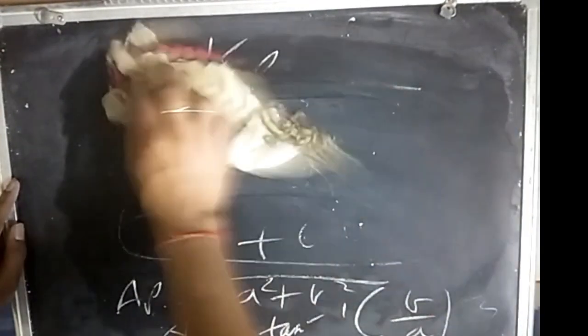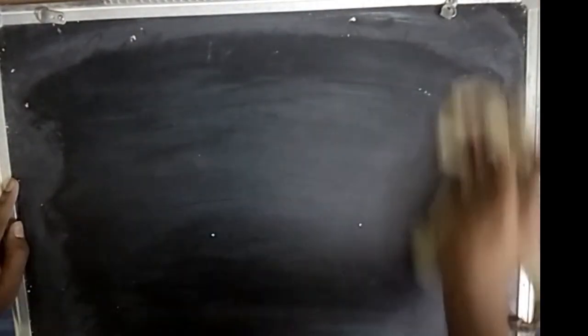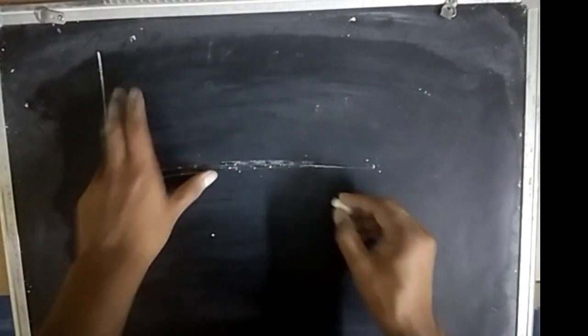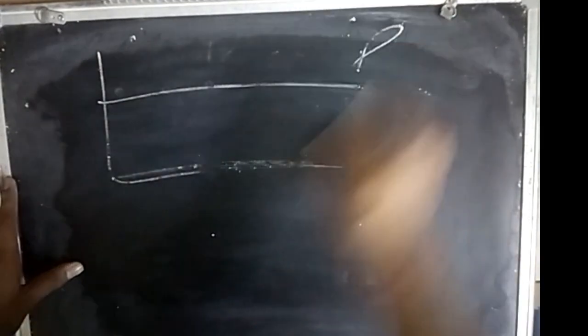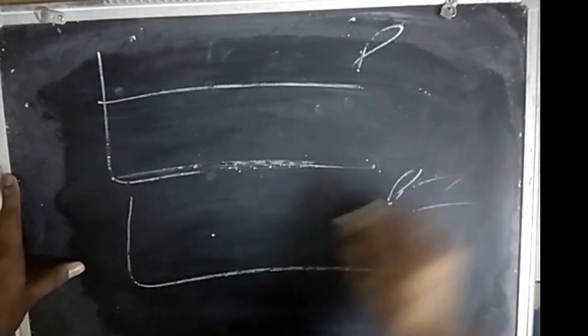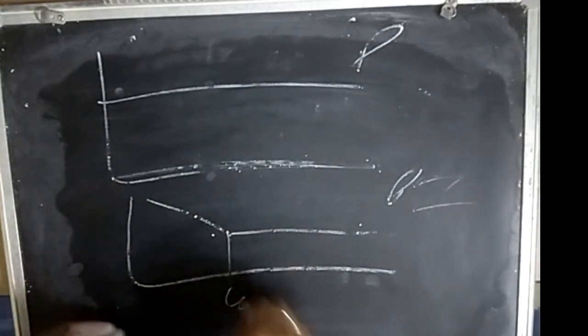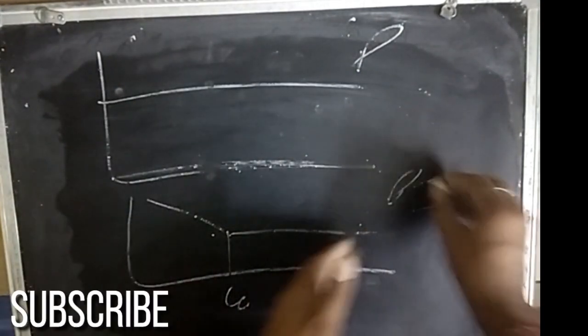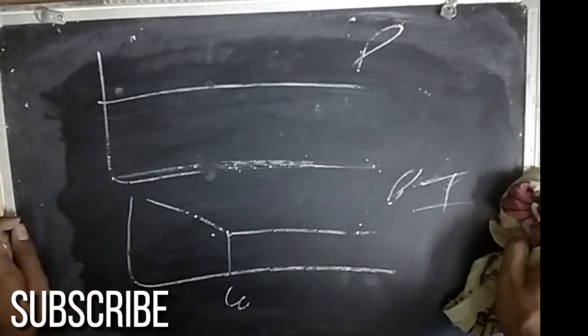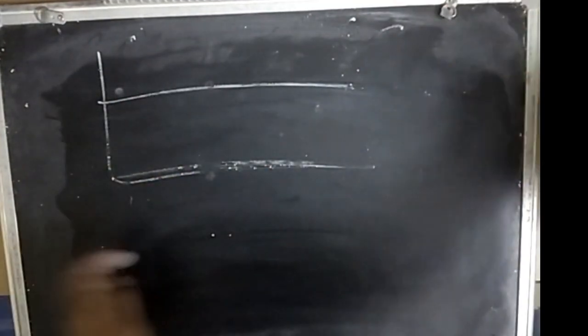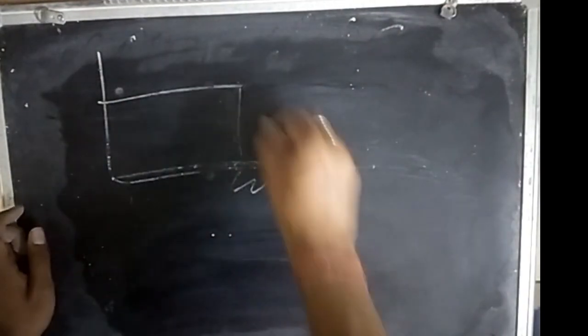These are the two simple things, and you can do it for any system and get their amplitude ratio or phase difference. For P action, let me list the graphs. For P action, it is this. For PI, it is first decreasing, then straight, at corner frequencies. Then for PD, just do this till some corner frequency and then go up.